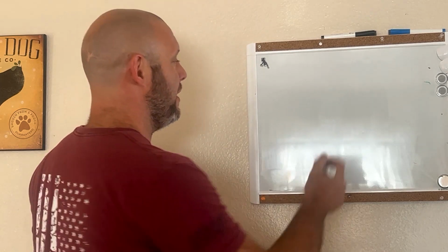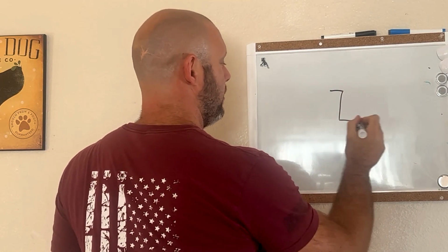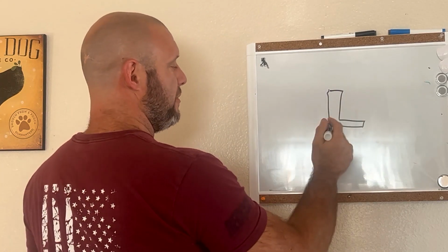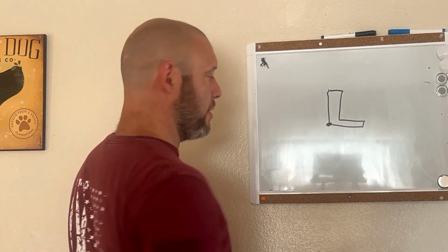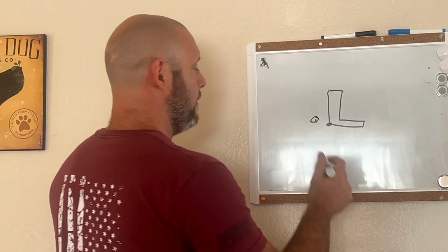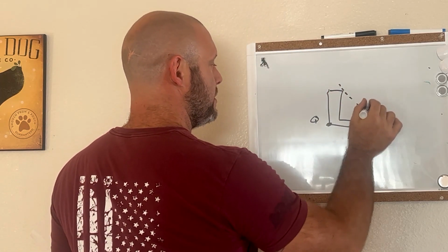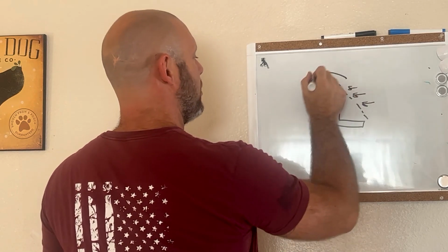So when an engineer is designing a retaining wall, what they're imagining is the moment of failure at this point right here. And again, to quote engineering models, they call this point Q. And they're imagining how much of this pressure, this lateral soil pressure, creates the overturning.